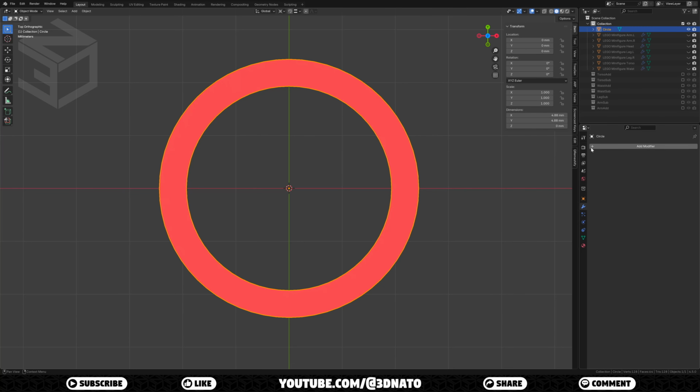On Modifiers, add Modifier, Generate, and add a Solidify modifier. Set thickness to 4.32 mm, offset to 0, and apply the modifier. Now press F2 to rename, and rename it hand.r.